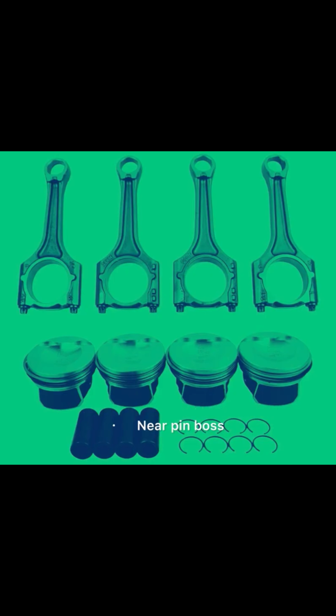What materials are used in piston rings? Cast iron, ductile cast iron, steel alloys, stainless steel, faced with molybdenum or chrome. 10. What is ring side clearance and how is it measured? Space between ring and groove, with a feeler gauge.